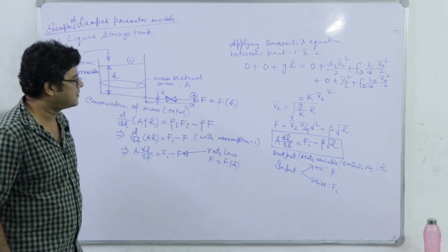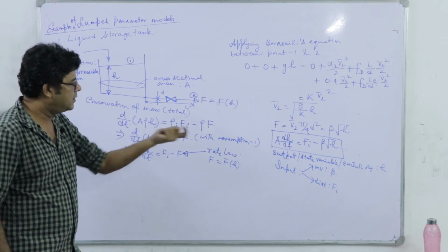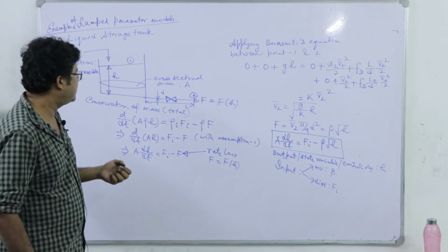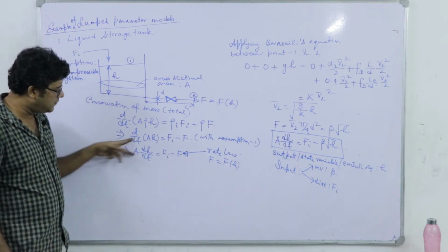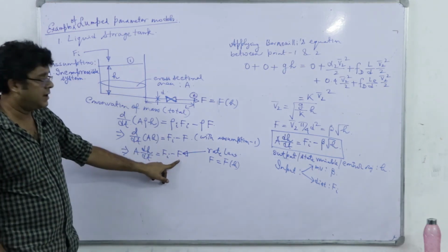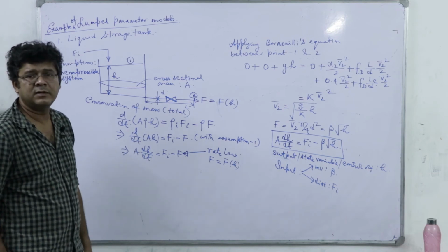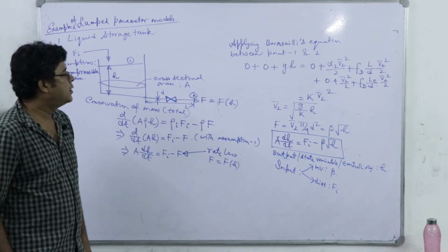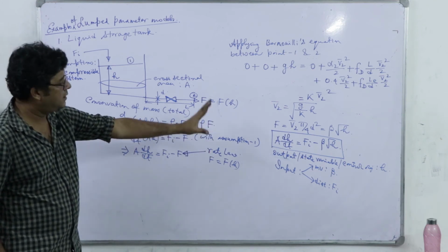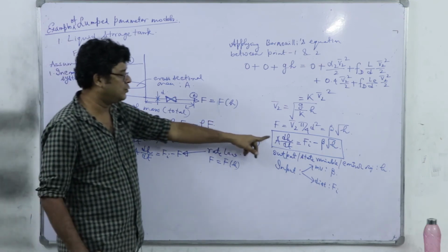you are basically adjusting beta and you are getting the controllability of that system. But here, if you look into this system without using the rate law, F will be your manipulated variable and Fi will be the disturbance, H as usual will be the state variable. So this is my input, not the input output model. Input output model is problematic here to solve this equation.